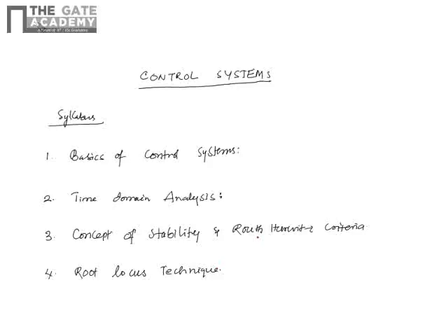First is the Routh-Hurwitz criteria. For any characteristic equation of a system, we can find the stability of the system. If it is unstable, that means there are roots lying on the right half of the S-plane, and we can also find the number of roots lying on the right hand side of the S-plane by using the RH criteria.